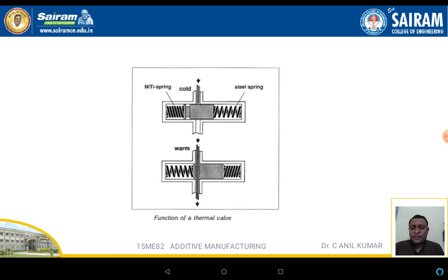Depending upon the expansion as well as the contraction of the spring, the plunger starts moving right and left. Once it starts moving towards the left, as the plunger has a stepped portion, through that stepped portion automatically the port will be opened and the fluid flow will take place. Once it is under contraction, the stepped portion will be moved towards the left, which blocks the fluid flow.